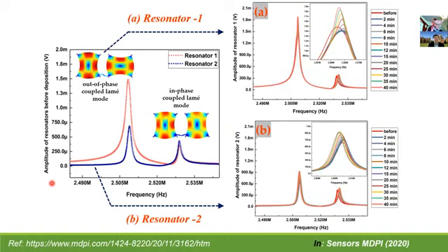And this graph shows the frequency and amplitude shift of the coupled resonators in response to the soot particles deposited for about 40 minutes on the resonators. So when I was doing this experiment, the frequency peaks didn't appear to shift with increase in particle deposition. So I wasn't sure if the resonator was sensitive at all to the particles deposited.